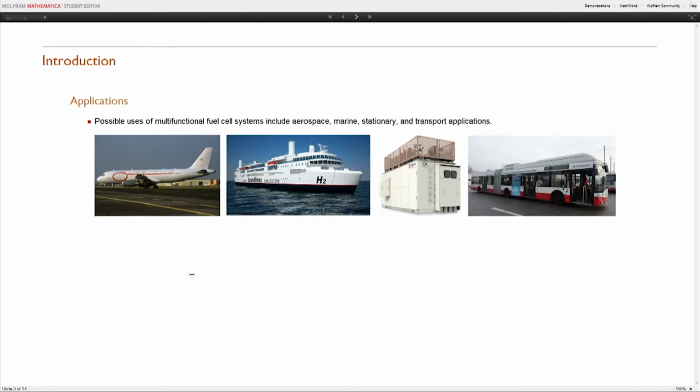This is a high voltage DC battery powered bus which has a fuel cell range extender, and the most tricky stuff is here. It has a roof-mounted fast charging device, so that there are certain bus stops on its route where there are a few minutes standing time, so this bus can always have an induction rapid charging mechanism to recharge the battery during the stop. And if it's not enough, then the fuel cell will come up as a range extender. This product is already commercially available.